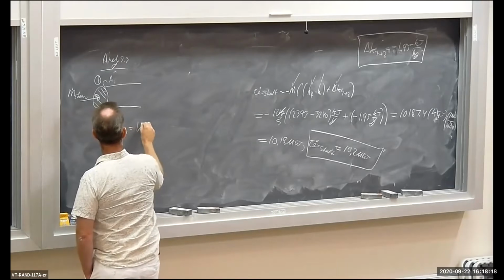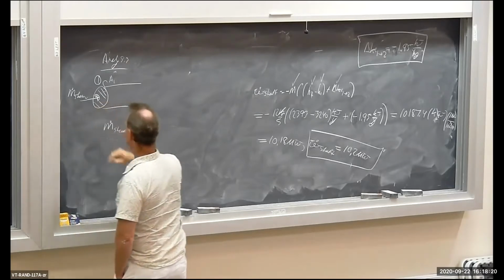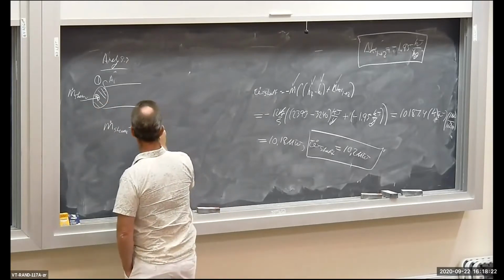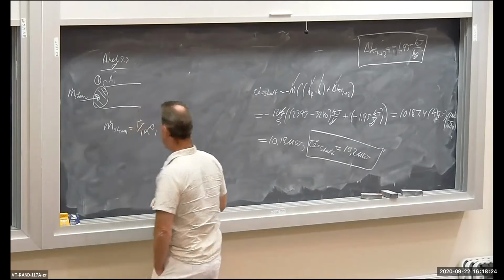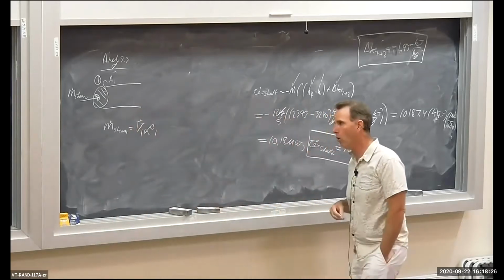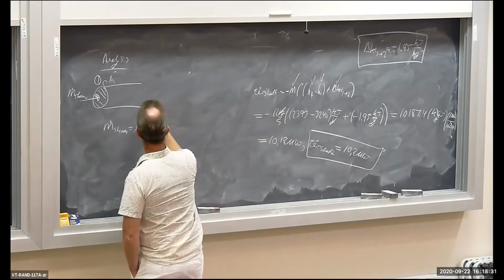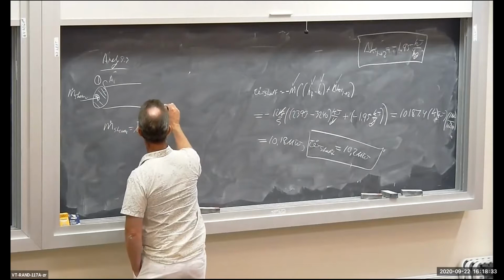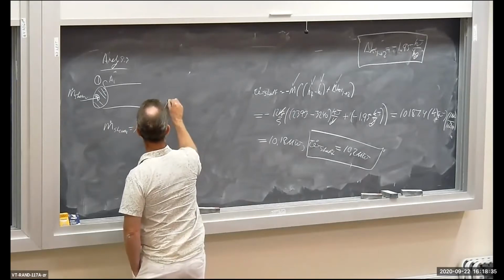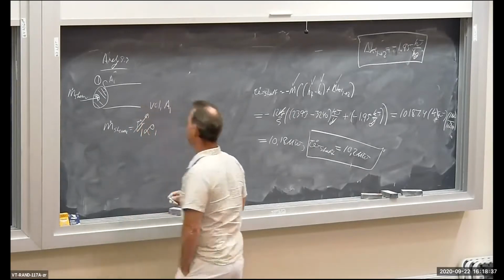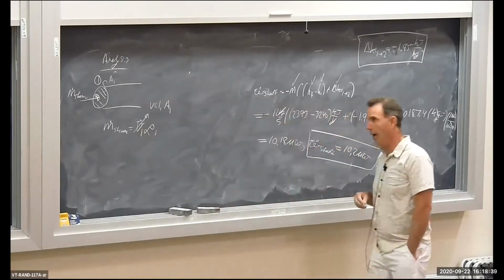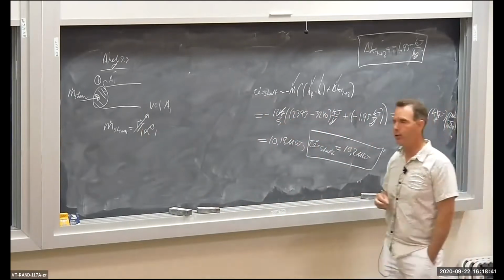is going to be equal to the volume flow rate at the inlet times the density of the steam at the inlet. So V dot rho 1. Now V dot, that's equal to the velocity at the inlet times the flow area at the inlet. Okay? And density is 1 over specific volume.